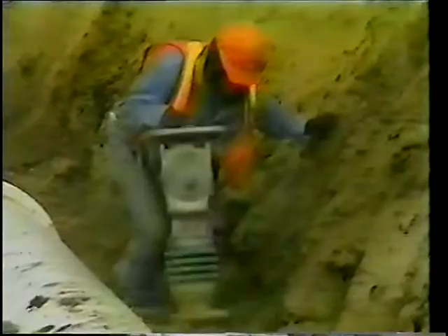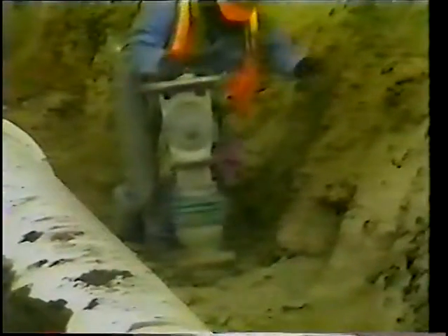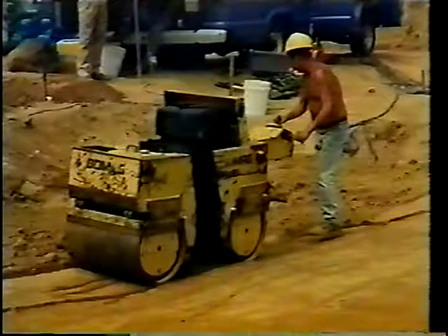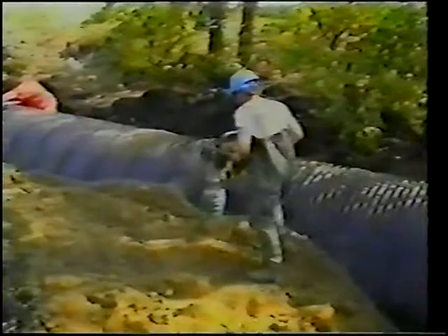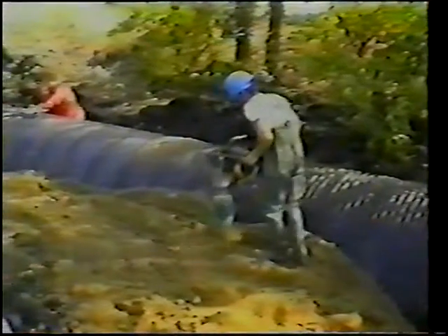The method of compaction is often determined by the type of soil being compacted. Smooth drum or pneumatic tired rollers compact the soil by pressure. Impact tampers can compact to 95% standard Proctor if the soil is placed in lifts of suitable thickness for the soil type and compactive methods used.